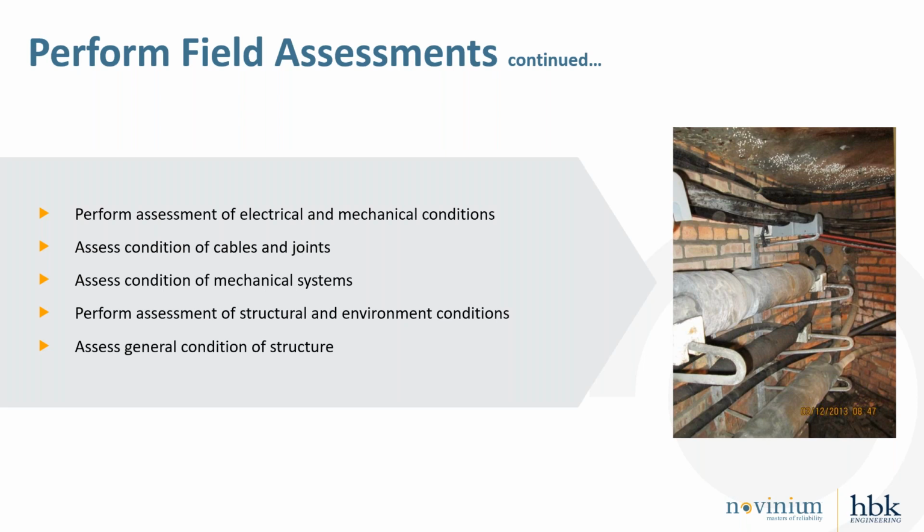a second safety check. That's a cursory visual inspection from the top for safety hazards that may be present within the manhole on the electrical system. If none are found, the crew will proceed with the full assessment. The electrically qualified worker will go in and perform his portion of the assessment, and then they'll trade up and our engineer will enter the manhole and perform the remainder of the assessment.